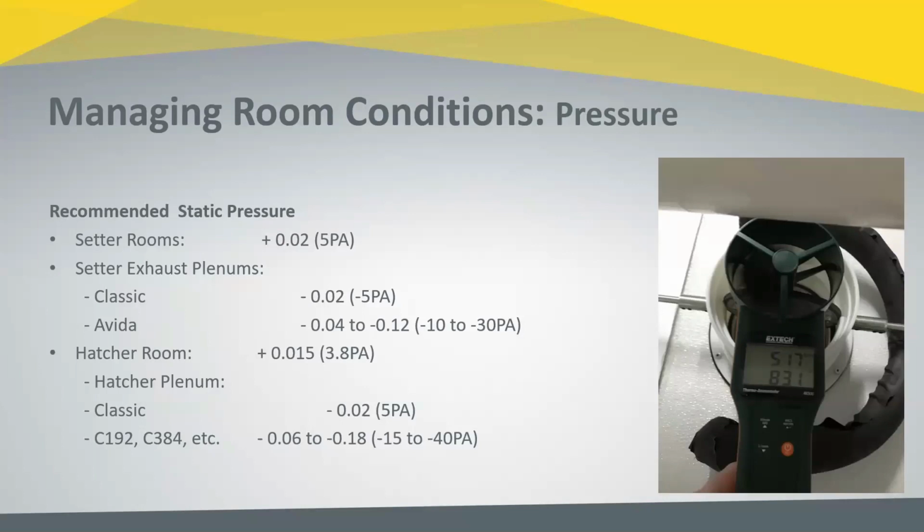Another quick question. What are the recommended CFMs for a classic hatcher? So on a classic hatcher, it is a machine that doesn't necessarily do a great job, on the older classic hatchers, of cooling itself strictly with the water cooling that's internal to the machine. So it relies heavily on airflow to provide some of that cooling source. And so the key with that particular hatcher is to be capable of providing in a range of 10 to 15 CFM per 1,000 egg set capacity.